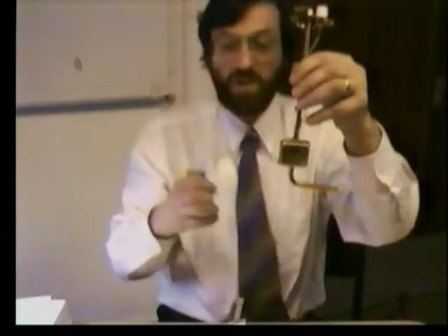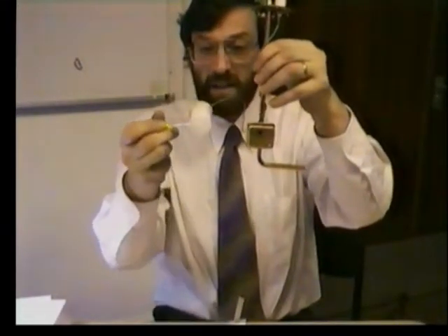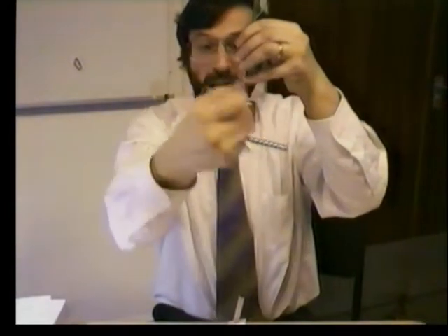In fact, it's a variable resistor. The idea is that as we change the position of the angular motion, we change the point where we pick up off that resistor. Thereby we have transduced volume to level to angular rotation to a variable resistance within the electronic circuit, and now we're getting something electrical.